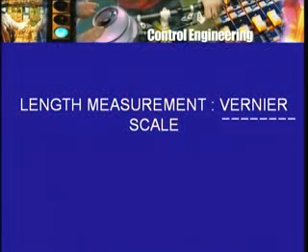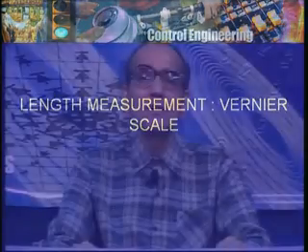simply because we know that earlier we could measure things to within centimeter or within a millimeter, because if one uses a scale, then you can barely see a millimeter on a scale. But then some person by name Vernier came up with an idea that resulted in a Vernier scale, and using Vernier scale now you can go down to a tenth of a millimeter, something which you cannot see directly, but indirectly you will say that your length measurement is now precise within 1/10 of a millimeter. And if I combine it with a microscope and so on, I may be able to increase the precision even more,